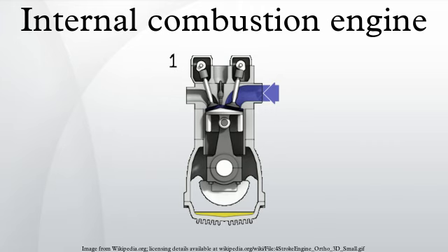A gas turbine is a rotary machine similar in principle to a steam turbine, and it consists of 3 main components: a compressor, a combustion chamber, and a turbine. The air, after being compressed in the compressor, is heated by burning fuel in it. About 2/3 of the heated air, combined with the products of combustion, expands in a turbine, producing work output that drives the compressor. The rest is available as useful work output.